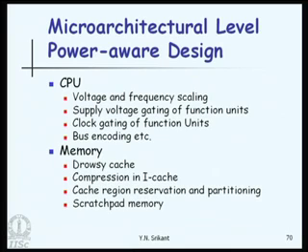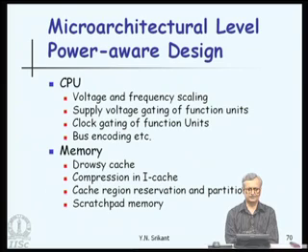It is possible to compress information in the instruction cache. If we do so, the instructions will all be in a compressed, encoded state, so we will have to decompress the instruction before it is executed by the processor. Obviously, compression happens in the compiler, and decompression happens when the instruction is going to be run on the processor. The power consumption for decompression should not be very high.